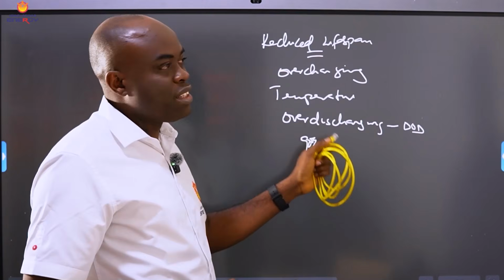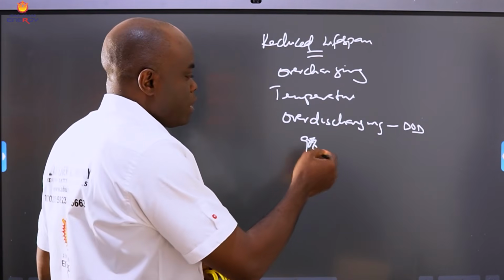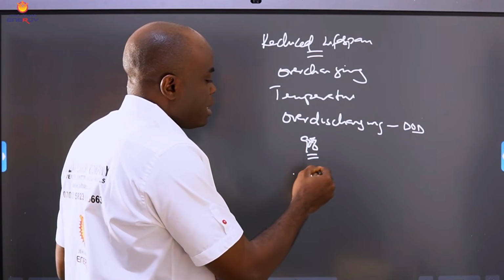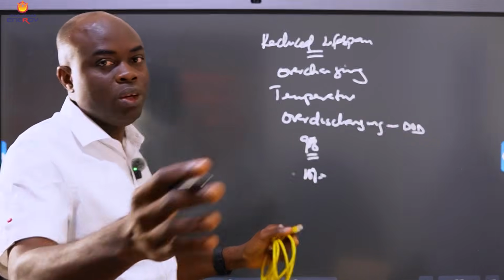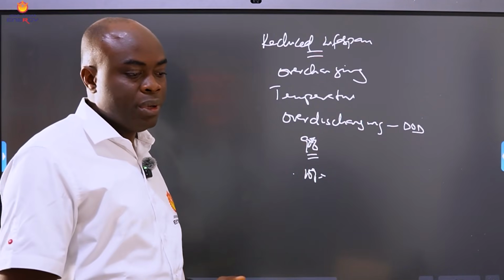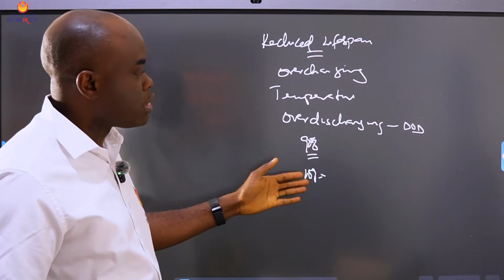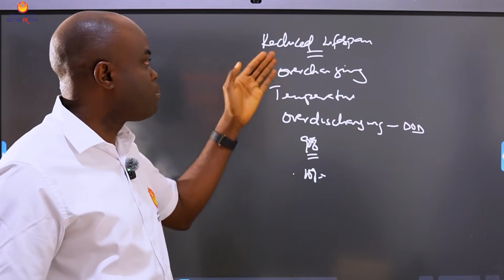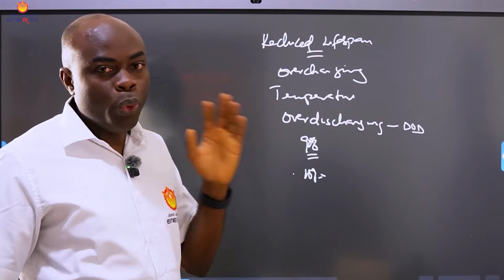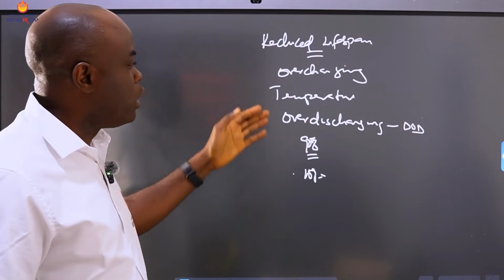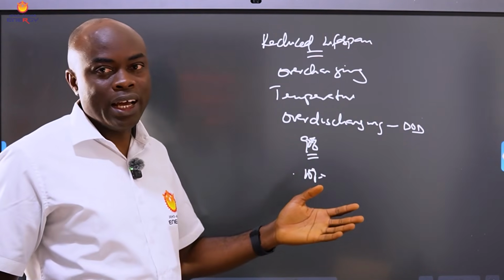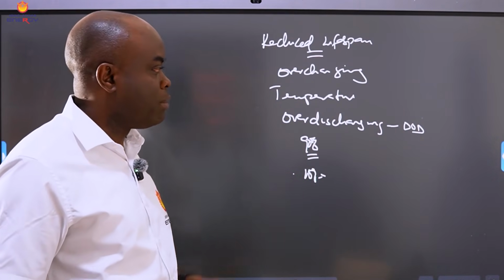And when the battery gets to that depth of discharge, say for example 90%, once it's just 10% left, it disconnects the battery. It disconnects the load first, then your battery remains until there's a charge into it to raise it up. So the lifespan of your battery will be reduced when you don't have a communication cable connected to your battery.